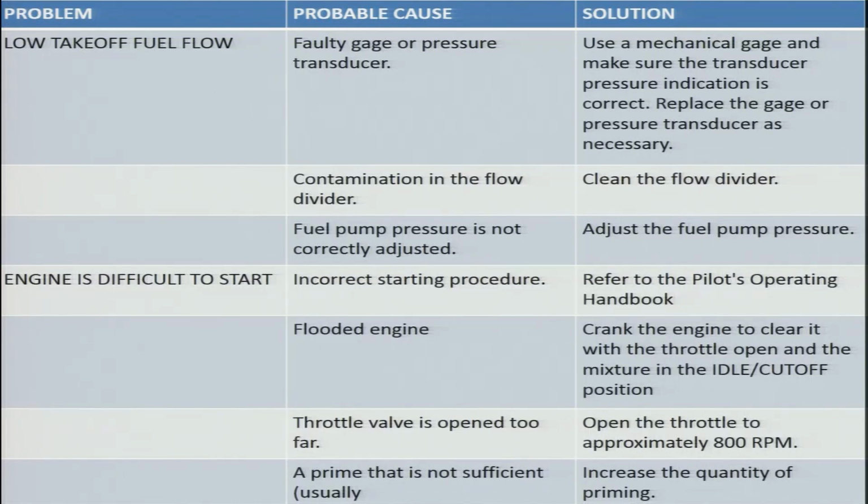In case your starting procedure is incorrect, then we need to refer to the pilot's operating handbook, to the manufacturer's recommendation, to correct our starting procedure and start the engine as per the manufacturer's recommendation. Another reason might be a flooded engine. Your engine has been supplied with more than the required fuel. In that case, crank the engine to clear it with the throttle open and the mixture in the idle cutoff position. So, a flooded engine needs to be cleared. It is cleared by cranking the engine with the throttle open and the mixture control in the idle cutoff position.